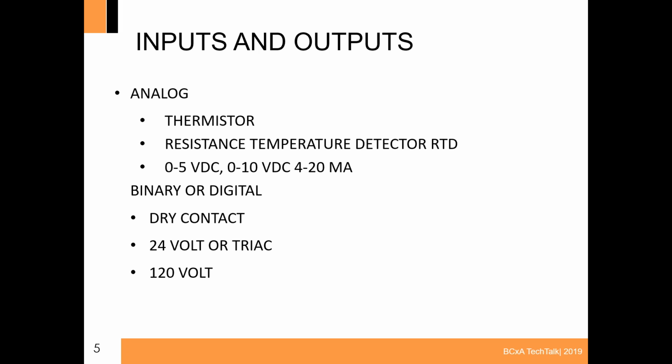So an example might be a filter differential pressure switch. There's like a diaphragm that is being pushed by the air pressure difference before and after the filters. And when the diaphragm makes contact, it brings those two pieces of metal together, and now the circuit's complete. And that's how the control system knows that the filter is ready to be changed. A current switch that senses current works in a similar fashion. Those aren't active. They don't have voltage. That's why they're called dry. So they're making a circuit, but they're not putting out voltage.